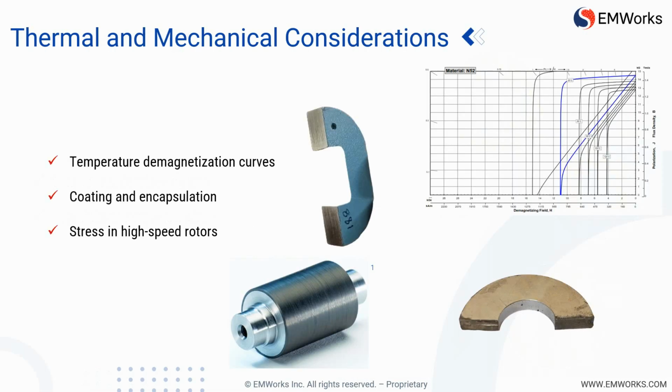Integrating permanent magnets into electromechanical systems requires a multidisciplinary design approach, combining electromagnetics, thermal analysis, mechanical integrity, and manufacturing constraints. From an electromagnetic perspective, the selection of magnet grade must align with the flux density requirements and temperature profile of the application. Engineers should use BH curves at elevated temperatures to assess potential demagnetization under load or fault conditions.